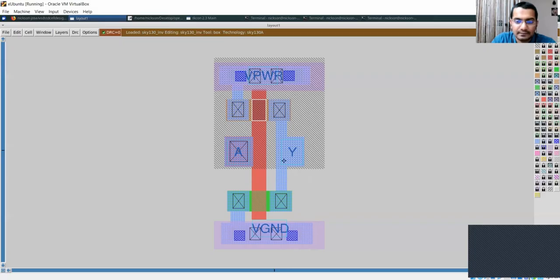Okay, so this is how you do it. So when I say we drill the contact holes over here, we are actually making this area accessible to the top layers. Okay, that's what we exactly do. So the next step is to remove the photoresist and now deposit a thin layer of titanium nitride.